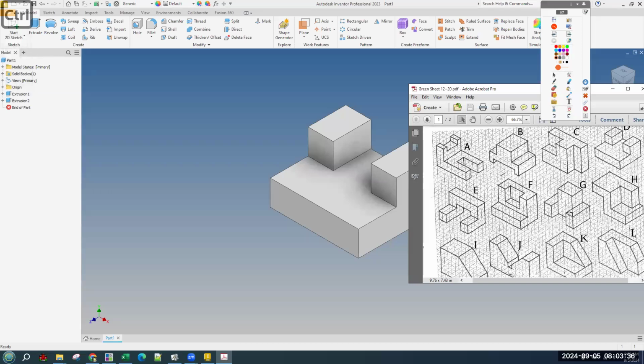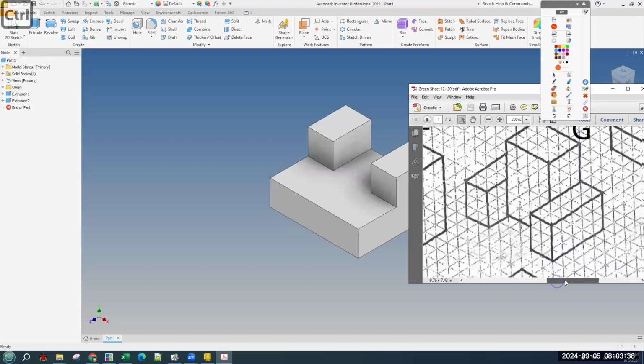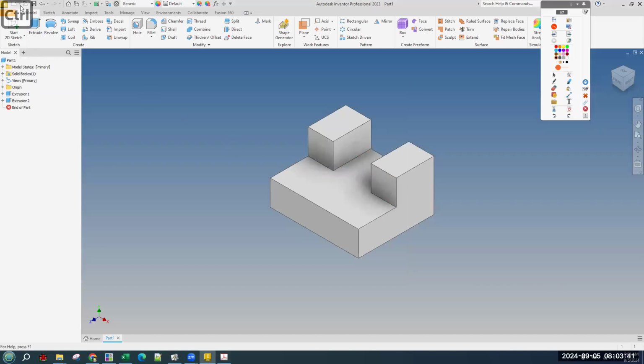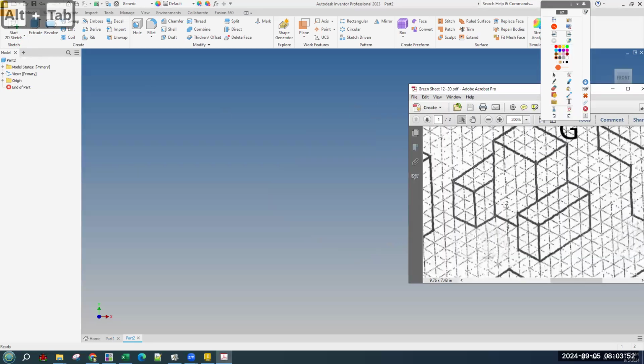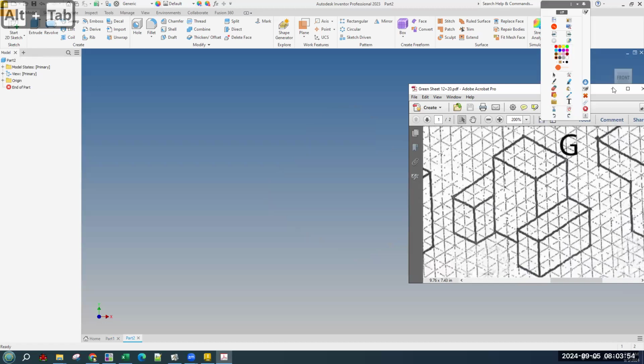Okay. G offers some challenges. And the way I'm going to do G is, again, all additive, meaning we're just going to make a sketch, extrude it, to create material and just continuously create material. There's no cutting required. And the method or the path I'm going to do for this is the first thing I'm going to make is this sort of right arm. I know it's on the left shape, but for me, this looks like those pillows, those giant pillows with the arms.